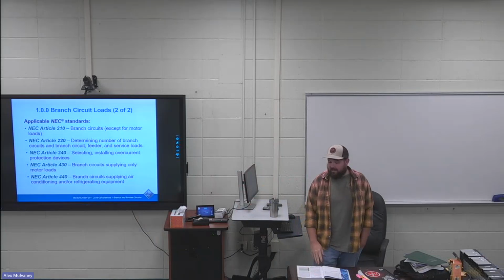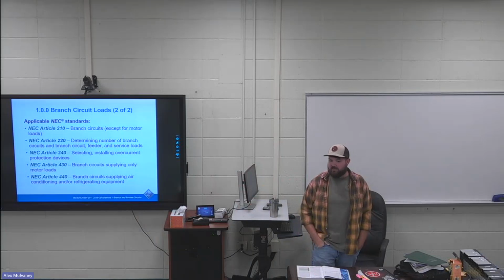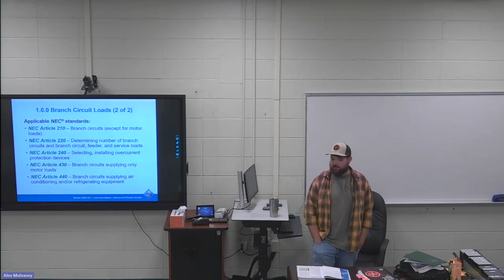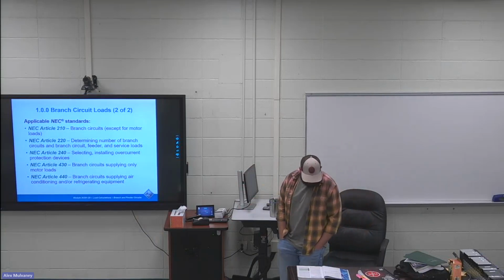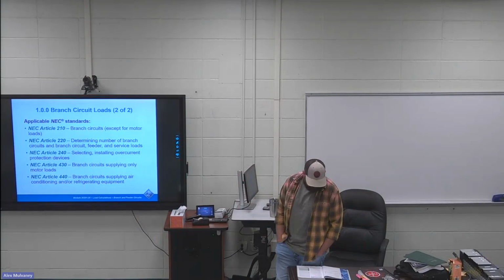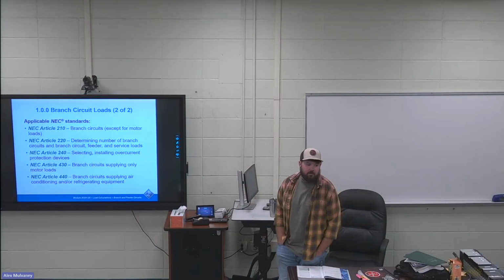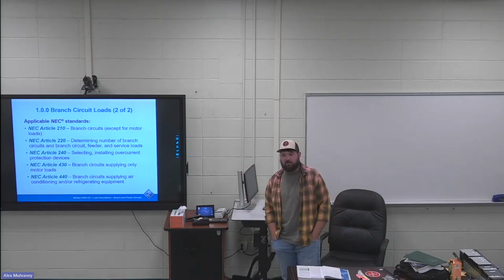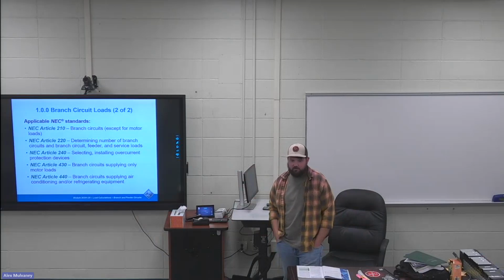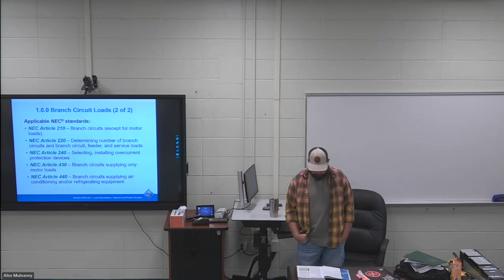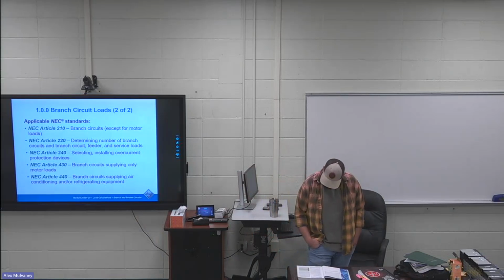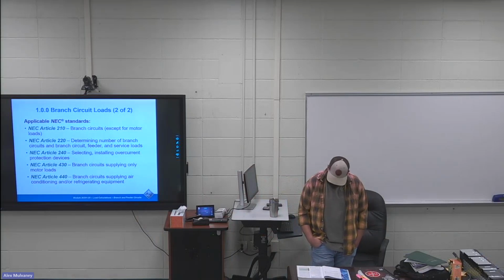Continuous load. I don't have any of these highlighted, but these are going to be important. We're going to use continuous load a lot. You're going to be looking for continuous load in these questions because it will completely change the answer. The continuous load is a load where maximum current is expected to continue for 3 hours or more. So this would be like a lighting outside of a business. Like you turn your lights on for your business at night. Everybody expects that those lights are going to stay on for 3 hours or more. Stuff like that. Everybody should know what an outlet is, receptacle, overcurrent.